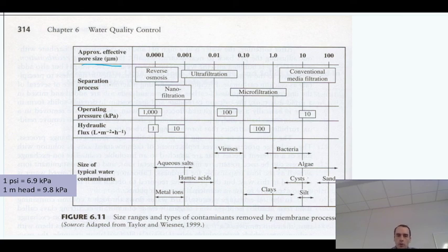With a decent microfiltration membrane, if you're above 1 micrometer, maybe you're not removing all bacteria, but you can certainly call it microfiltration at 0.22 micrometers, and that should remove just about all of the bacteria, and so on. Right? So you have ultrafiltration, you've got nanofiltration, all the way down to reverse osmosis, where you're really getting down to less than nanometers, so the angstrom level pore size. So water can get through, but not much else can.